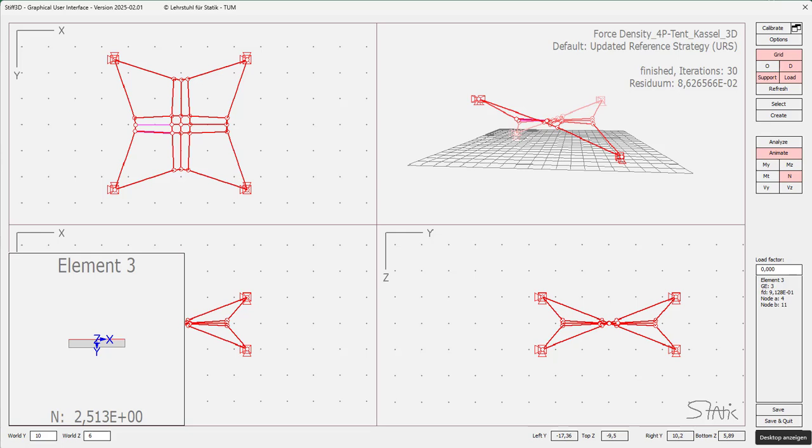The conclusion is that these kind of problems we can only attack with additional constraints. So for instance, controlling the lengths of the cables, in particular at the edges. Again, for a price, and the price would be that we just get close to our goal forces, but will never reach them, according to the constraints which force the solution to deviate from our ideal. That's what we have to be aware of, and with the knowledge about that, we may find nice compromises which make sense from an architectural or engineering point of view.